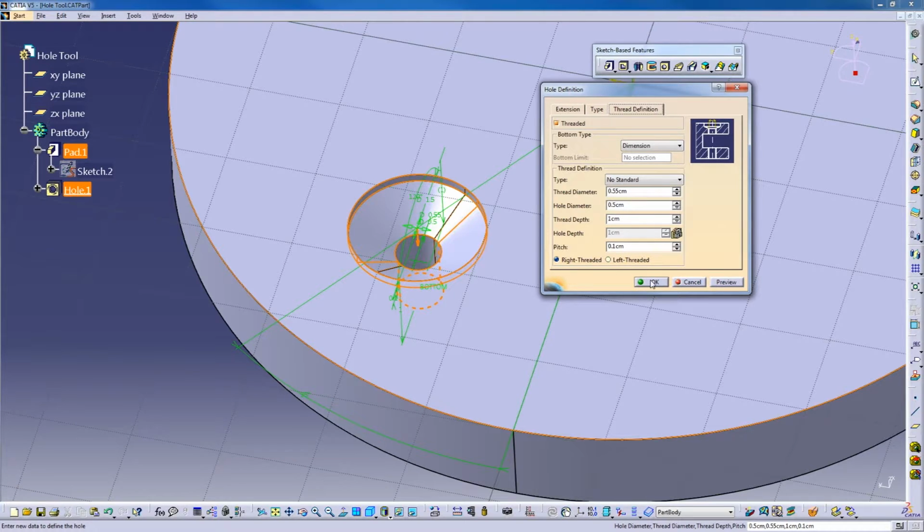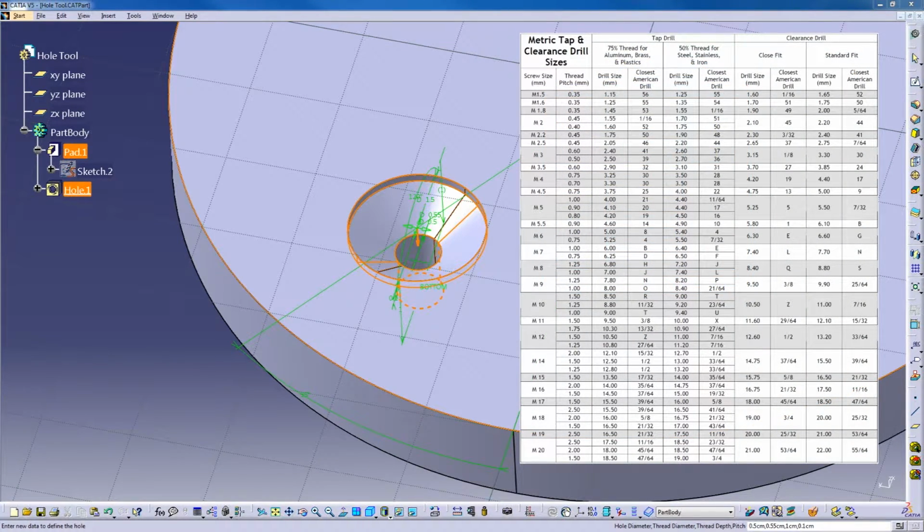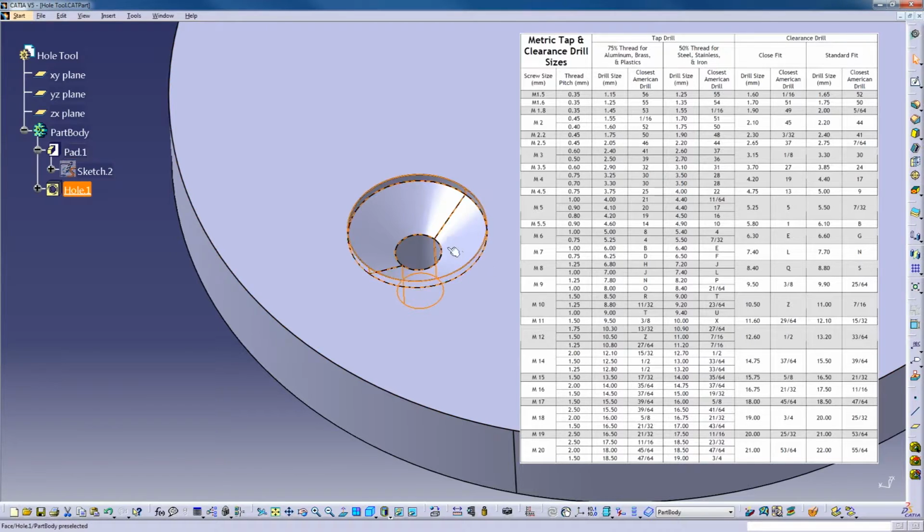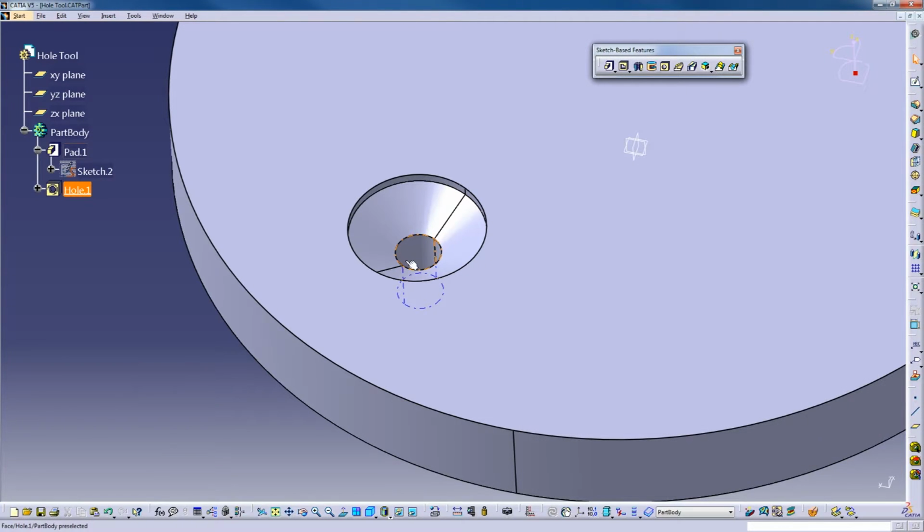Okay. One little piece to go along with that, look up the chart for holes, threads and taps. For example, if you have an M5 fastener, you don't make an M5 hole. If you make an M5 hole, the fastener is just going to drop in. There's not going to be any meat there, any material to make a thread with. So you'll find a chart, for example, an M5 would be conveniently a 4.5 millimeter hole.